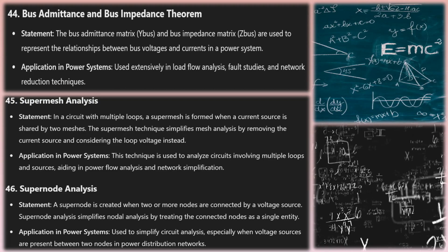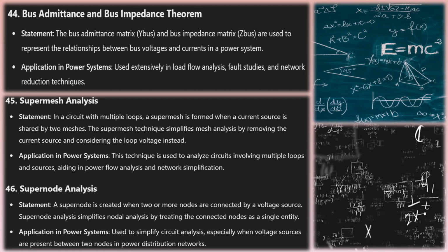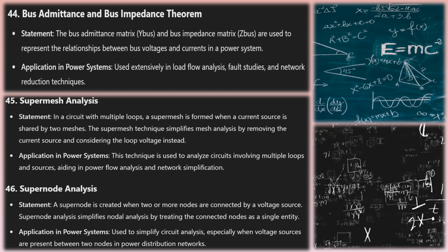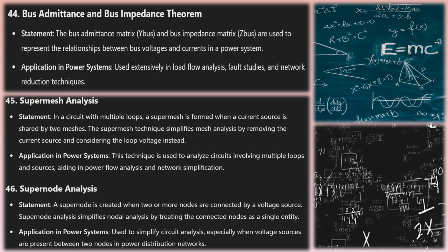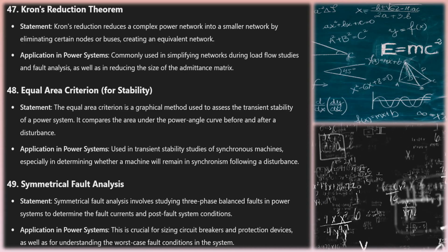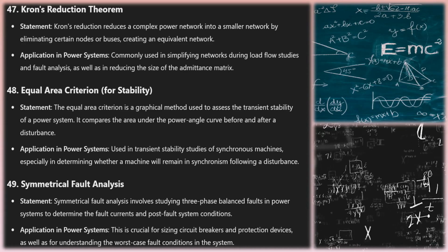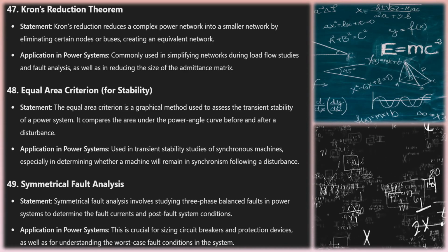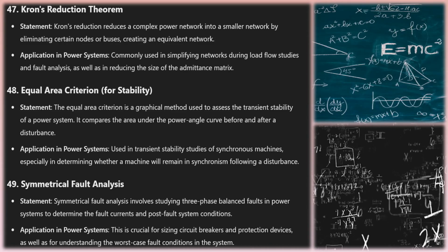Symmetrical components theorem. Any unbalanced set of three-phase quantities can be resolved into three sets of balanced components: positive sequence, negative sequence, and zero sequence. Application in power systems: extensively used in fault analysis, especially in unbalanced faults like line-to-ground or line-to-line faults.